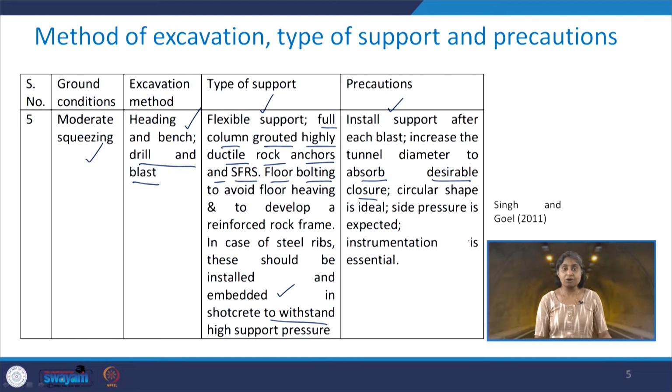In this case also the circular shape of the tunnel is ideal and side pressure is expected, and instrumentation is essential during and after the construction of the tunnel.